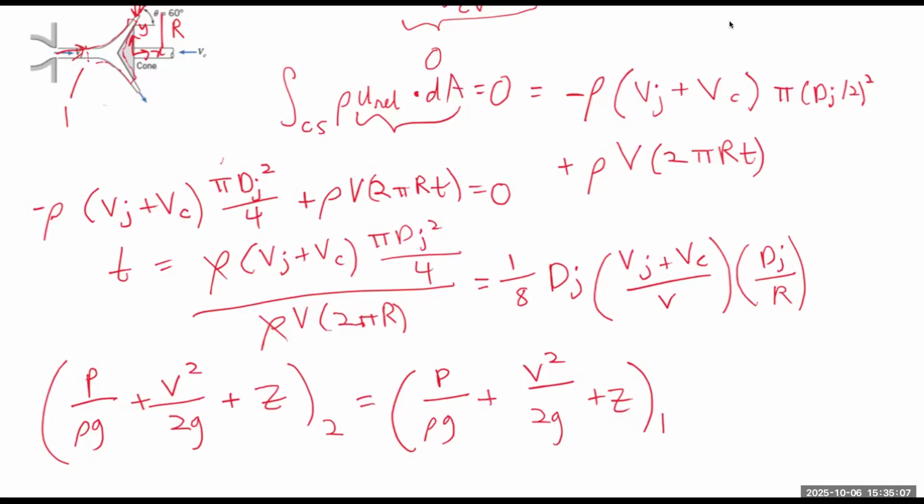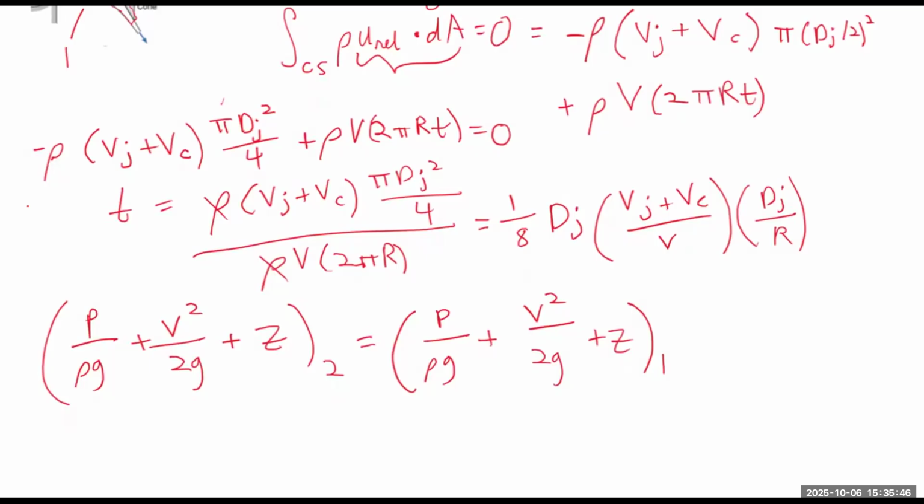Yes, a fluid system must be in steady state for Bernoulli's equation to be applied correctly, meaning the fluid velocity at any point within the system cannot change over time. If the flow is not steady, fluid properties like velocity and density will vary with time, and Bernoulli's equation, which assumes steady conditions, would yield incorrect results. So in this case, in order to apply Bernoulli's principle, we have to use a frame of reference fixed to the cone, as we have done from the beginning, so that the system can be considered in steady state. So using this frame of reference,